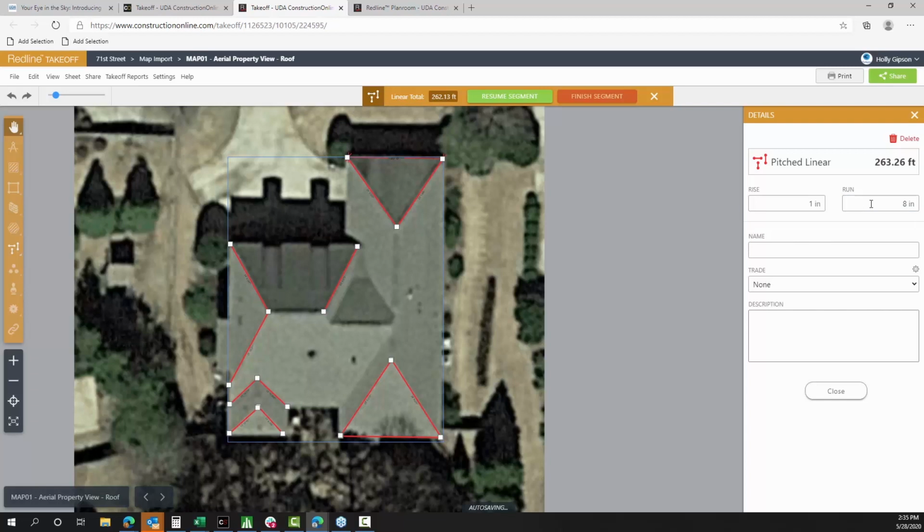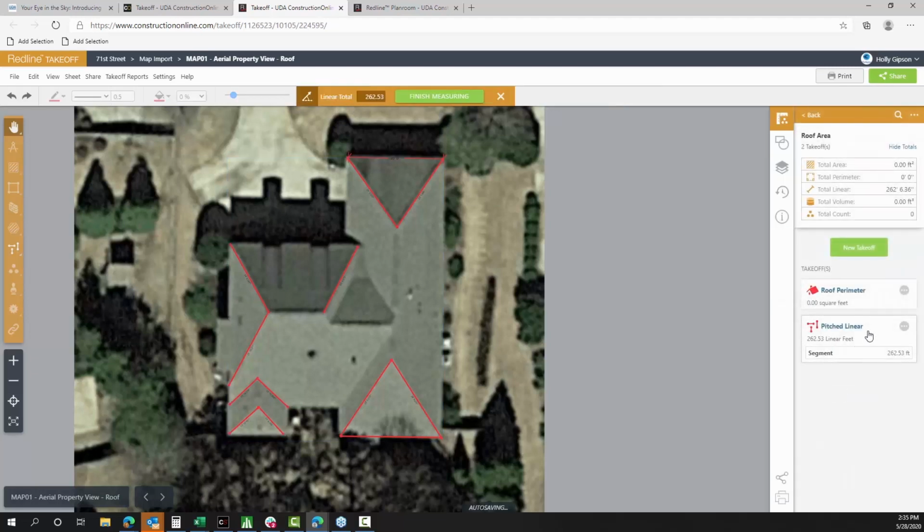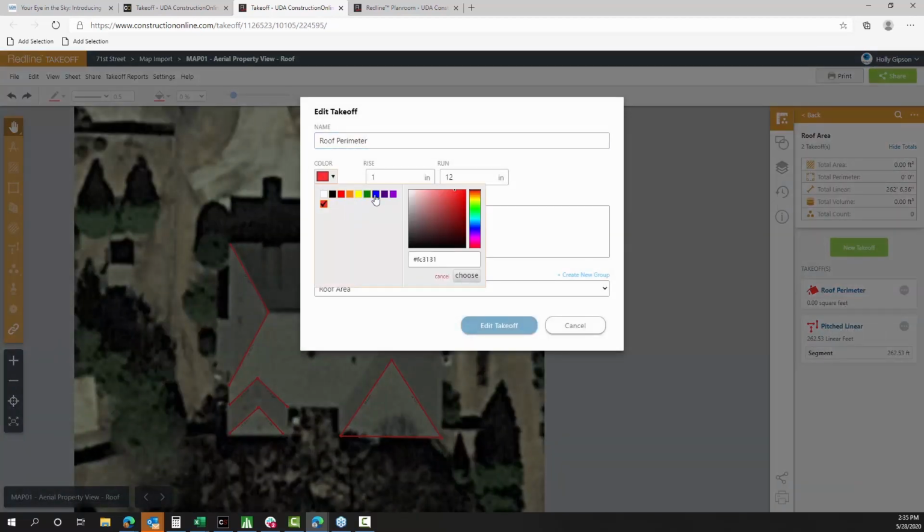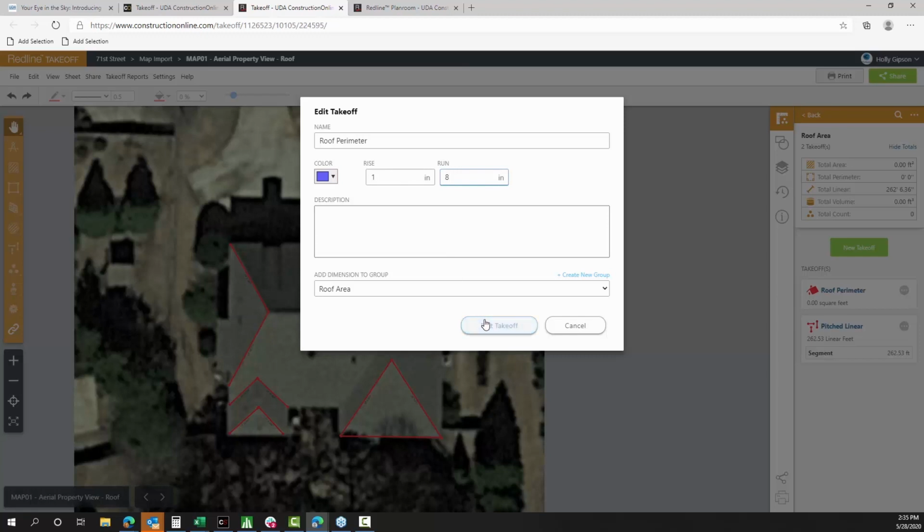Yeah, that's exactly right. Also something to note, you're not completely committed to the specific slope that you've selected here. You can adjust that if you realize that you've made a mistake, or if you need to make an adjustment. And this is something that you can set for each drawing that you do. In some roof plans the pitch will be the same, and in some cases certain sections of the roof will look a little bit different. So in cases where you need to adjust it, you can certainly do that for each one.